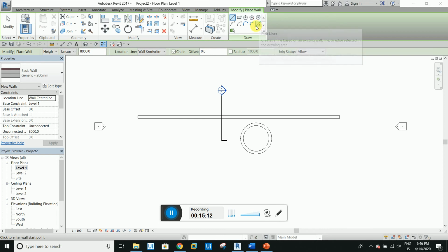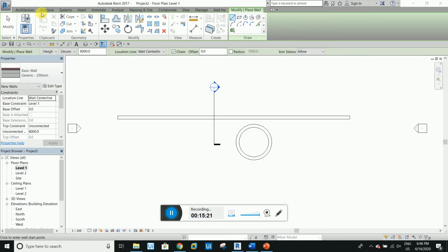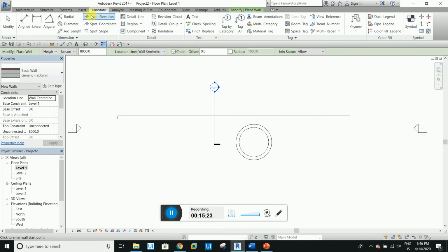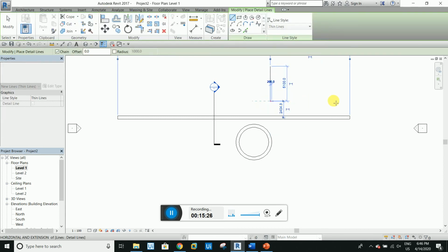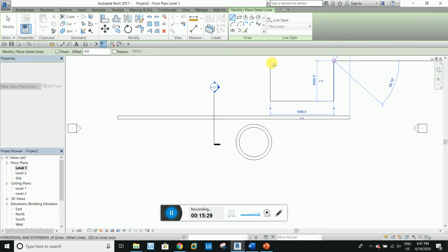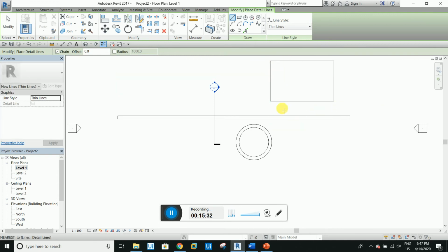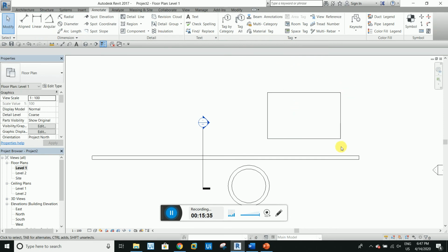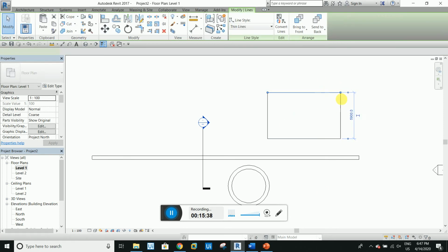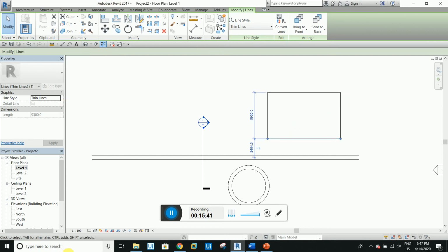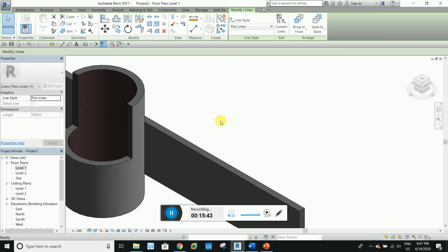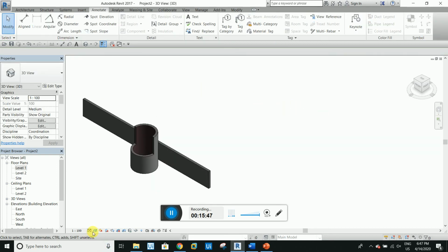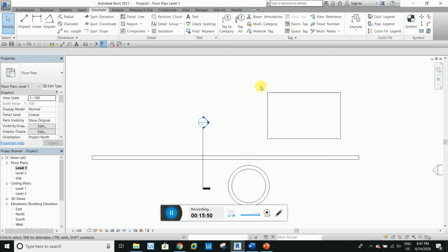So for this command, for example, if you import some AutoCAD plan into Revit, and you have some lines like an annotation, if I create a detail line like this, this is your bedroom, which you created in AutoCAD and brought here, and you want the walls. This is a 2D dimension line, so there is no height or anything. As you check here, you can make a 3D view. There is nothing here. So for this one, I want to create a line like a rectangle.